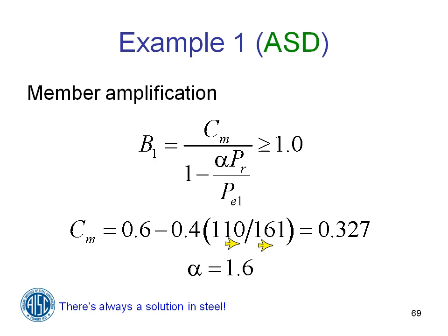Now, I don't think that if it were me, I would just jump right into it and do it without thinking. I think I'd want to do some bounding of the problem. Keep in mind that the whole idea behind the direct analysis method is that by using a reduced stiffness, you can eliminate calculating K. And so that's what you're trying to do. You're trying to eliminate the need to calculate K. So you might do a simple problem with whatever your old way was, and do it with the direct analysis method. See how close they come. Try to reconcile what's going on. But I would say, yeah, it should apply.